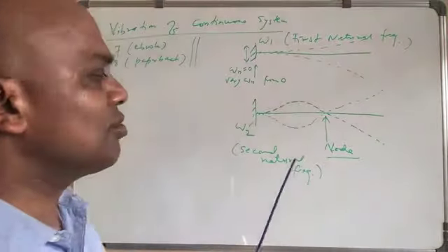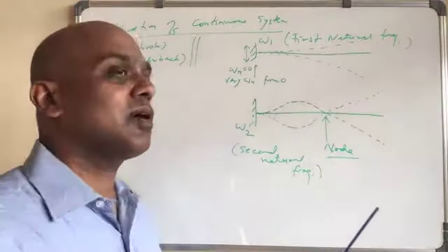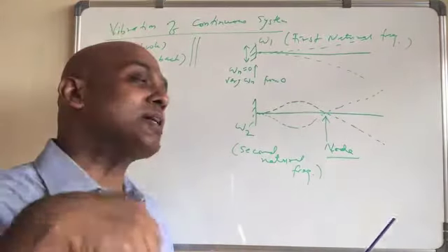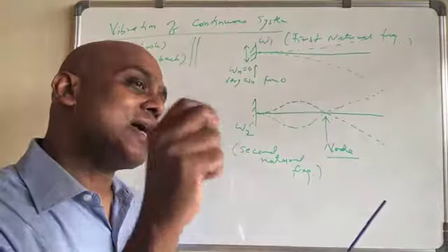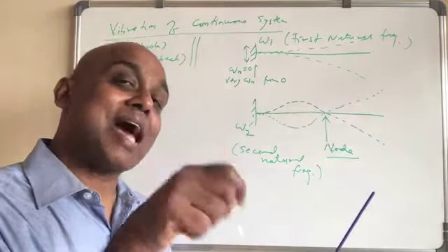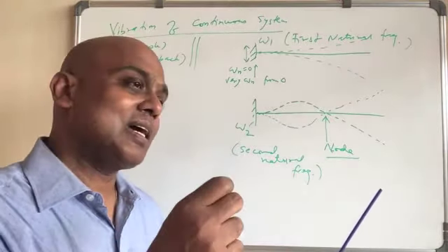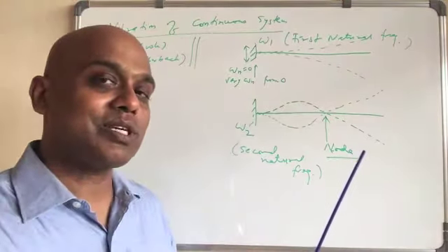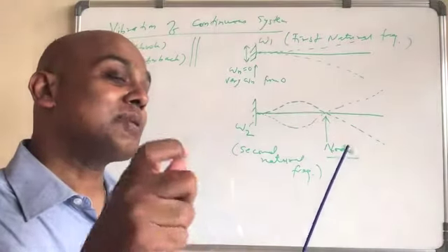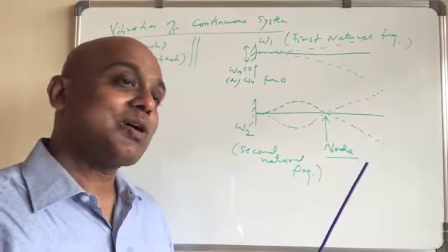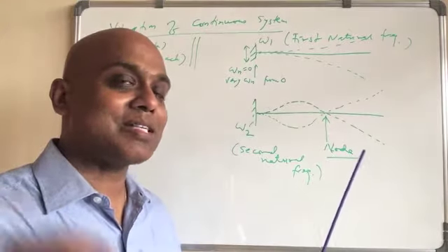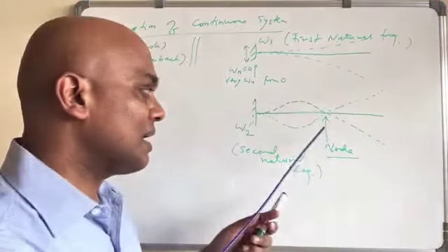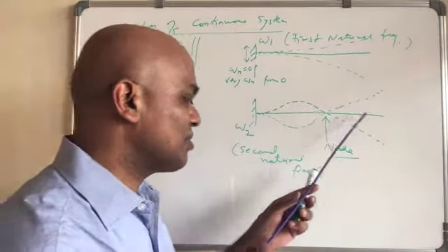Again, I am going to show this mode of vibration. This corresponds to omega 2. When you solve for beta, beta will be in terms of n, because beta x comes inside sine or cos. If sine beta x equals 0, then beta x will be equal to n pi. So you automatically have n there, and if you increase n, the number of nodes will also increase.